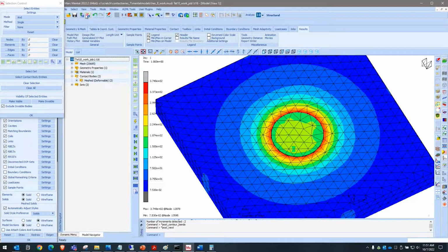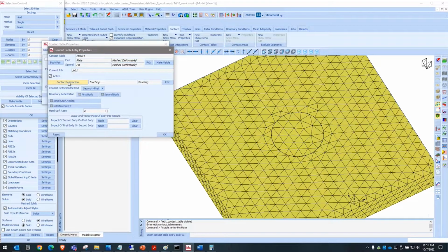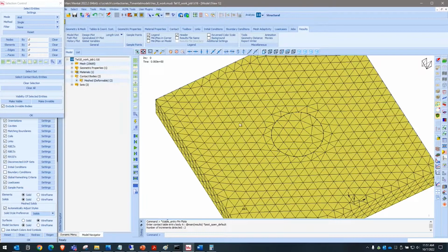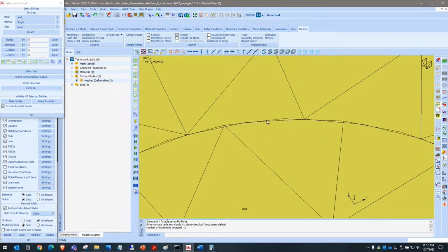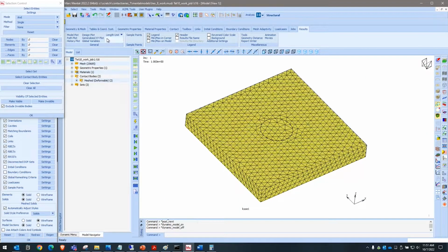Okay, so that said, this model, as I say, I did not use the interference fit feature. So the interference fit is off, it's physically overlapping, and then it forces it back onto that. So let's see if it's visual. That's the initial state, and you should see there's a slight movement radially outwards and radially inwards between the initial and then the stressed state for that interference fit.